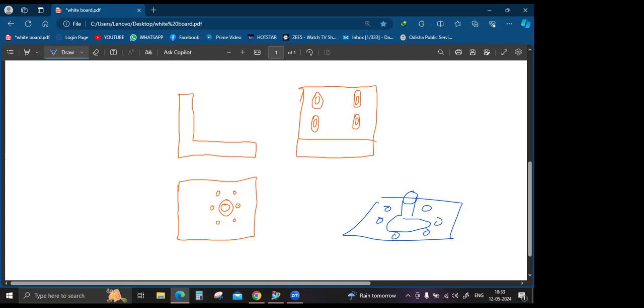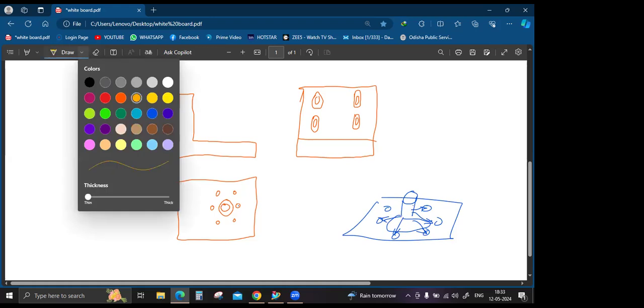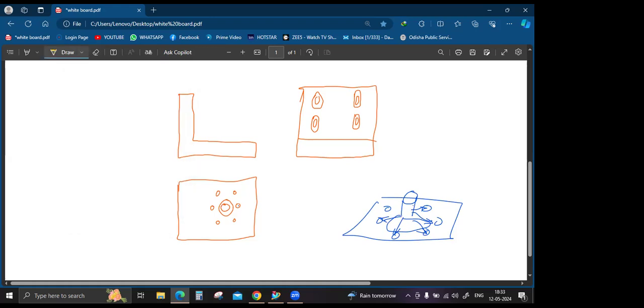Okay, this motor shaft and these mounting points are related. So that is why we have to take this circle as a reference. So this center line, and the vertical center line. So right now we have to give the datum over here, sir.